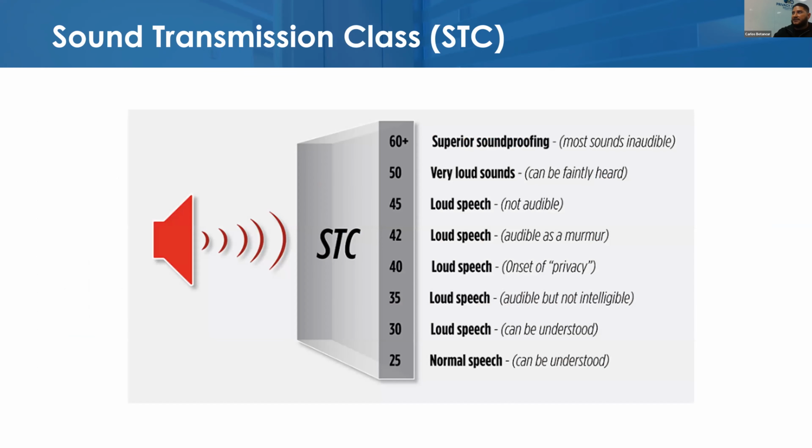And then here we have the STC, which was one of the questions. STC is a sound transmission class. It's basically a rating of how well a building partition is going to block sound in ceilings, floors, and windows, really any other surfaces that are rated. These ratings are listed in decibels or in volume. So what was tested was a 1/4 inch tempered glass with a 3/16 air cavity with a 1/2 inch laminated glass, and that gave an STC rating of about 39.